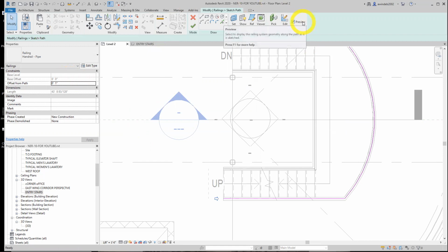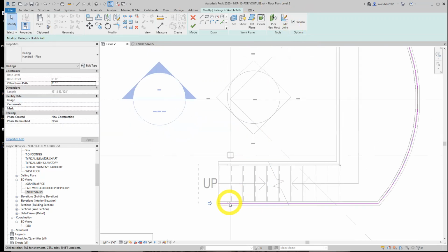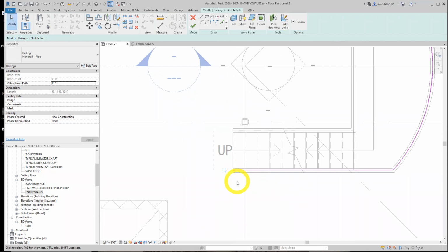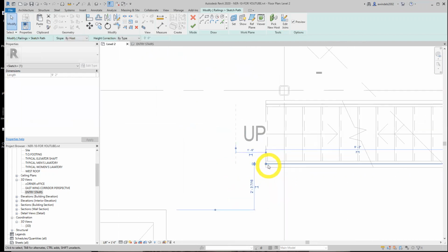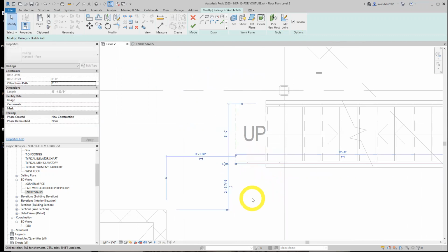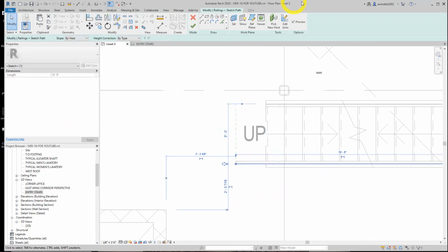That's new. So it's kind of showing what's going on. See there? Turn it on and off. That's showing where the railing will be. So let's zoom in. The magenta line's the key though, to where the railing's going to end up. We'll pick the magenta line and bring it over to the reference plane with a grip, just like that. Our preview lets us see it.